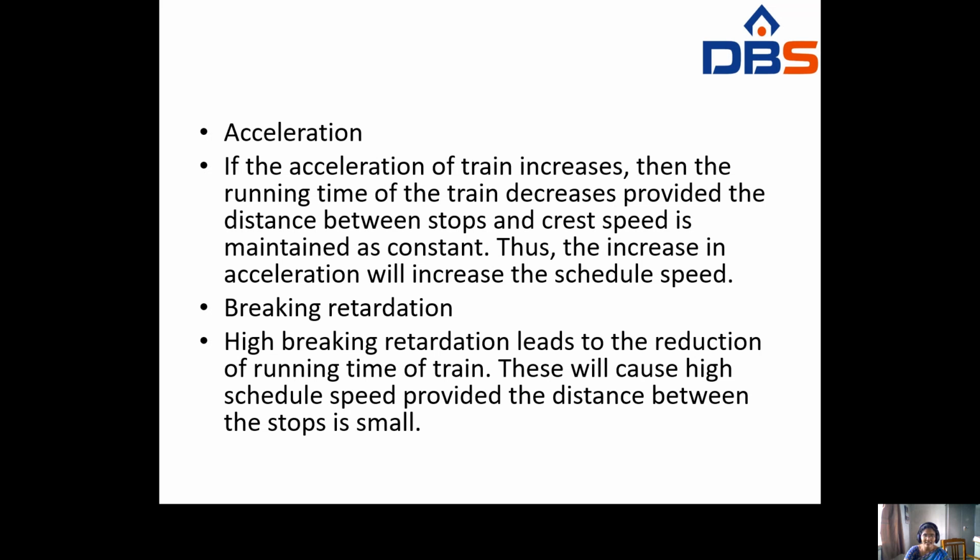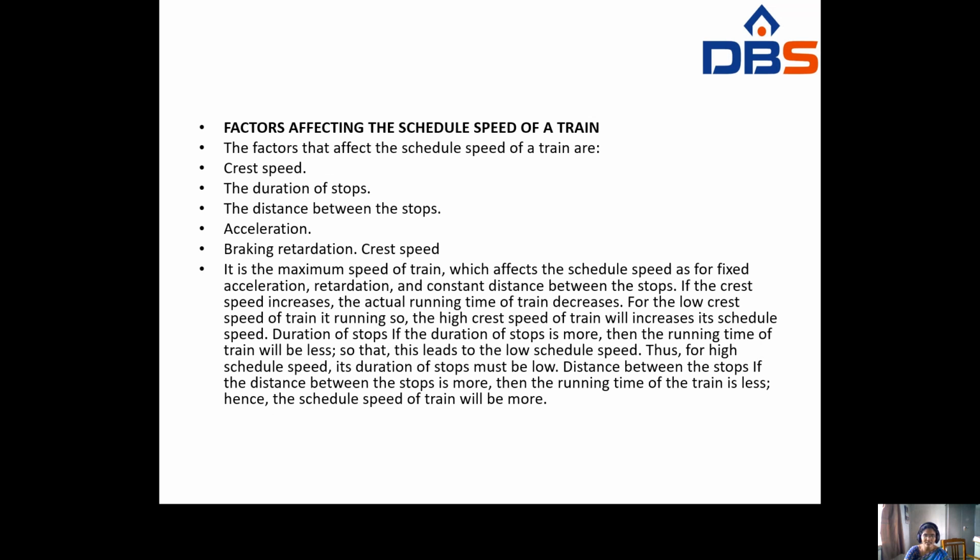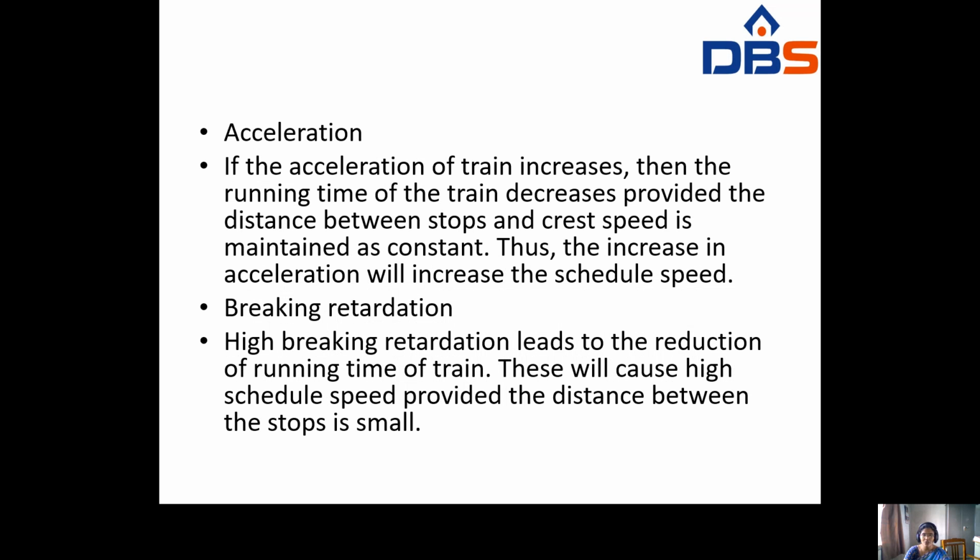Next one is acceleration. See here, we have discussed the crest speed, and the factors affecting it: the duration of the stops and the distance between the stops. Next we have to see how acceleration and braking retardation affect the schedule speed.